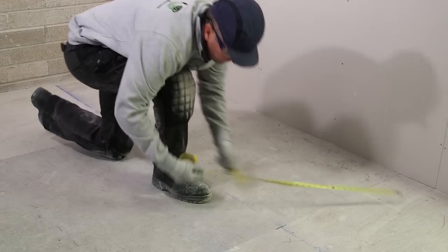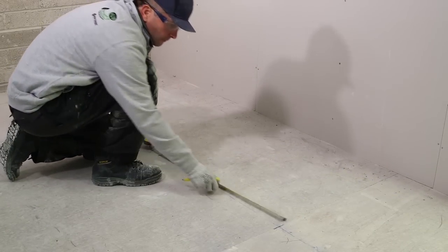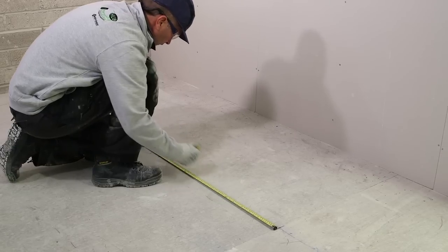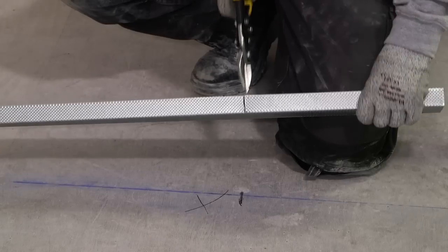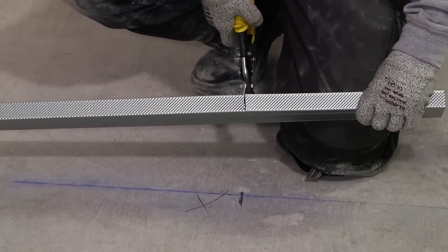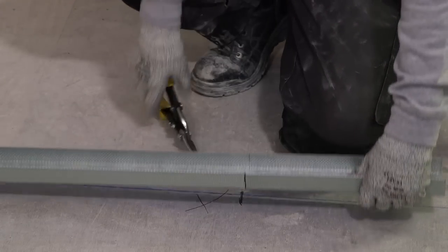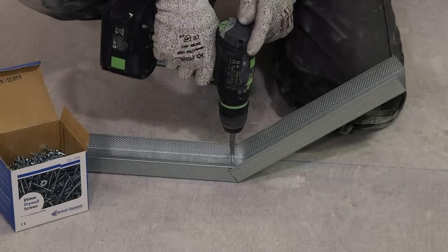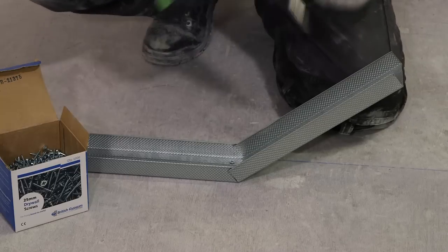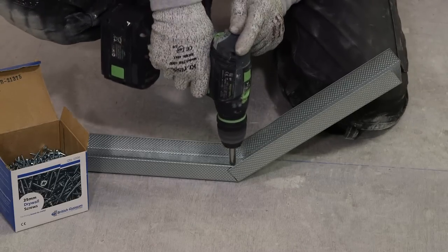Determine the wall position and make allowance for openings. Mark wall positions and doorways. For best practice, or to meet British standard duty ratings on partitions for doorway details, a bootleg detail can be installed as is demonstrated. With this detail, 4 fixings are installed within 150mm on either side of the doorway.